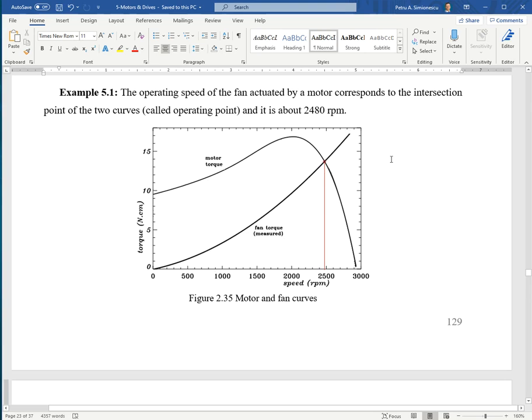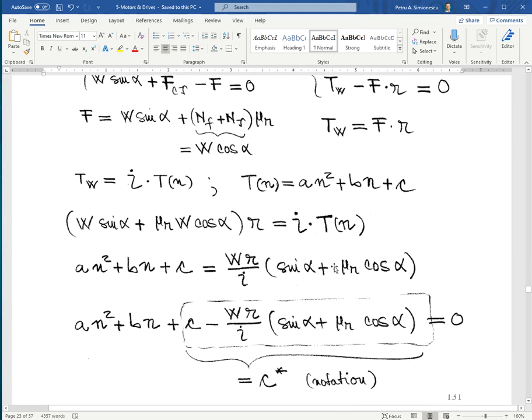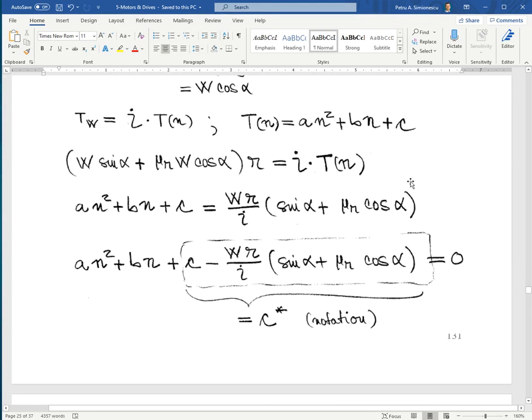Again assuming that I have them available analytically. So that's what I'm doing here. I have the engine torque analytically, and I set it equal to the resisting torque evaluated at the crankshaft. So that's why I'm dividing by nu. If there's any efficiency involved, then that efficiency is going to multiply this part of the equation.